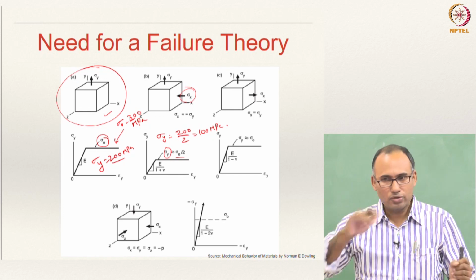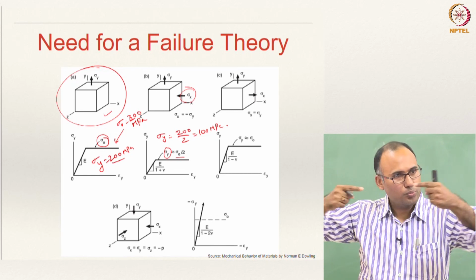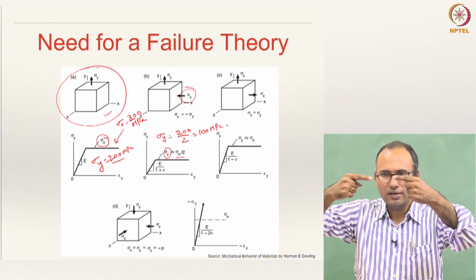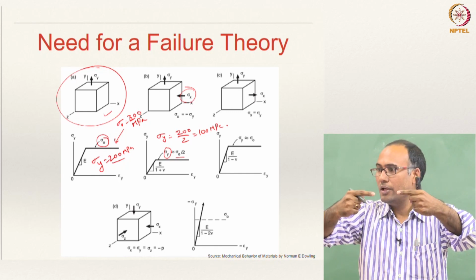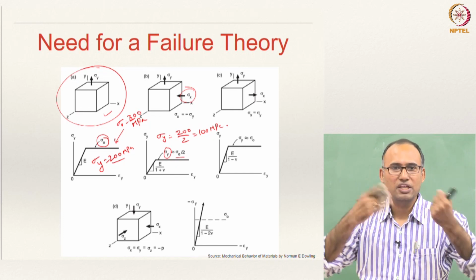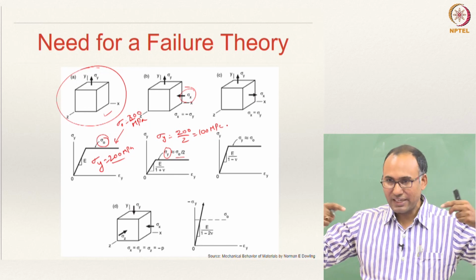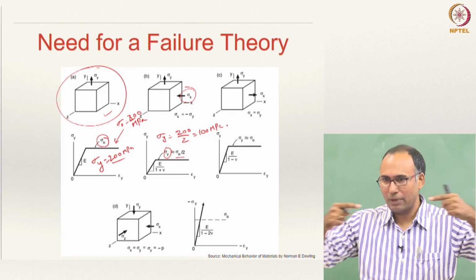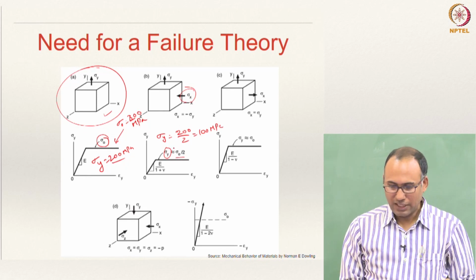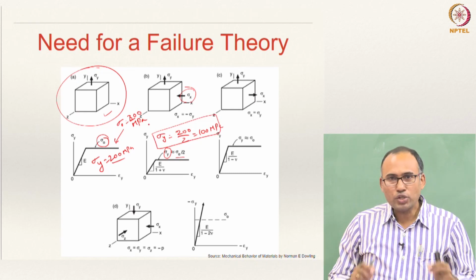So, think about it, you are applying this load and then you are pushing in this direction. When you are applying the load, because of the Poisson's effect, you have lateral contraction, right. Now you are pushing it by an additional compressive force, and hence we can say that we are helping the system to yield by pushing it with the external force, and hence probably the sigma y has come down.